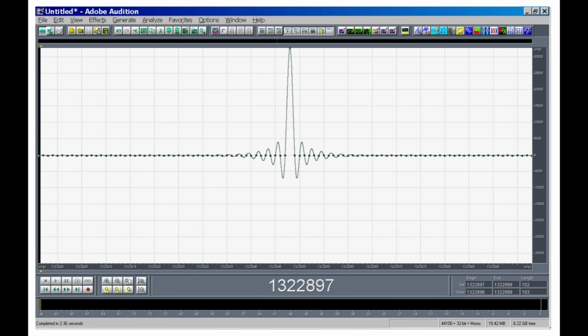Fade-in is still 0.1 seconds. Albeit the appearance of the waveform looks the same due to the analog waveform display of Adobe Audition. Looking carefully at the digital values, the small squares along the waveform, one now sees that the results are very close to a theoretical Dirac's delta function, and that no pre-ringing or post-ringing are any more significantly present.